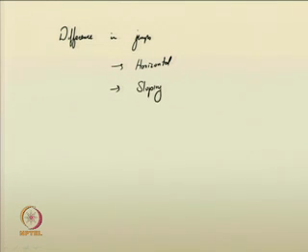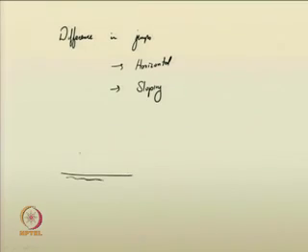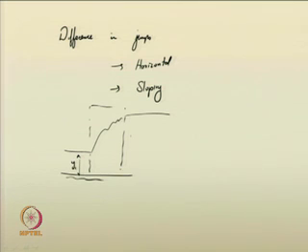As we suggested earlier, in horizontal channels, a jump is there and there is the horizontal channel, and if you take the control volume for the hydraulic jump, you take these depths, this is the pre-jump depth and this is the post-jump depth, y1, y2, right. And in this the effect of weight is neglected.